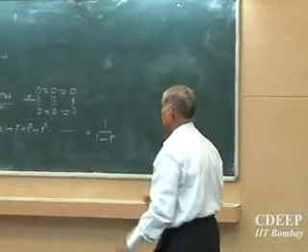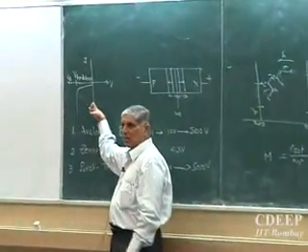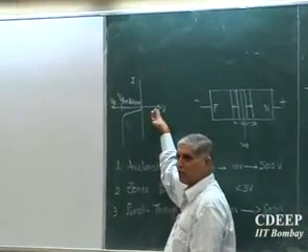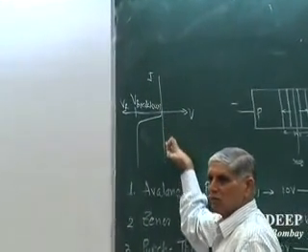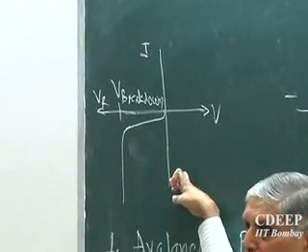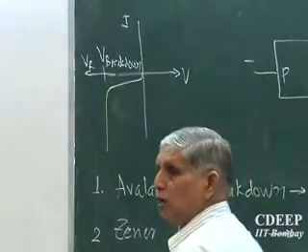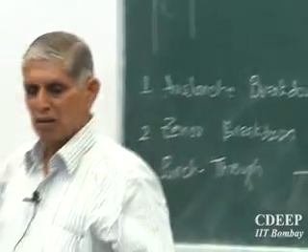So what is the limit of voltage up to which you can operate a device? The breakdown voltage. Any time you want the diode to be switched off in reverse bias and it turns on heavily, I don't want an on state for the diode under reverse bias. So I must protect my device by always staying below it. In electrical engineering, the word used for this is called what? Derating. Okay, so you should always derate the numbers.